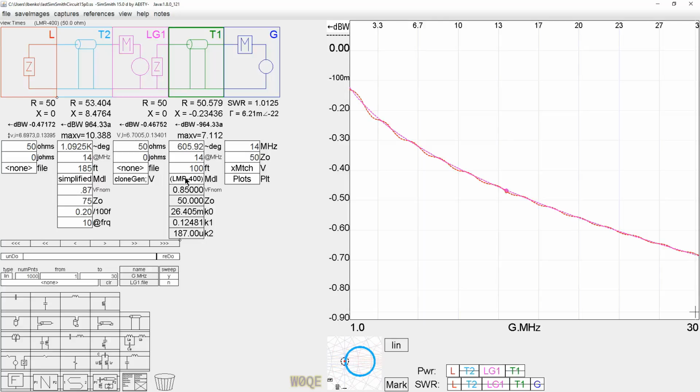Now, what's the downside to doing this? Well, the downside is, of course, that the free hardline probably does not come with connectors, and it's a function of how long the pieces you get are. Let's suppose you have to splice in the middle and you have to do something at the ends. So you're going to have to come up with connectors, or you're going to have to know somebody who can fabricate something to build a connector. It doesn't have to be a connector you take off, but it has to be some kind of a mating arrangement to be able to use this coax. But it might be worth a shot because it has lower loss.